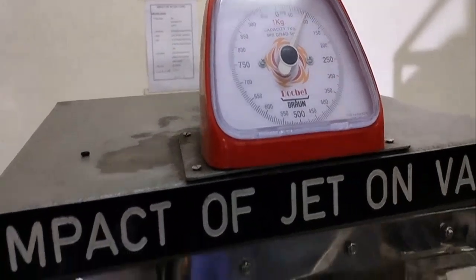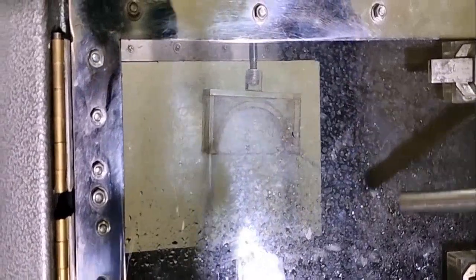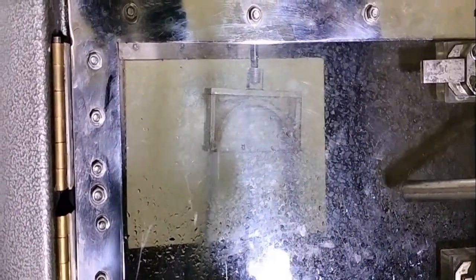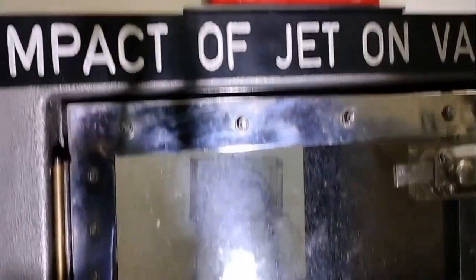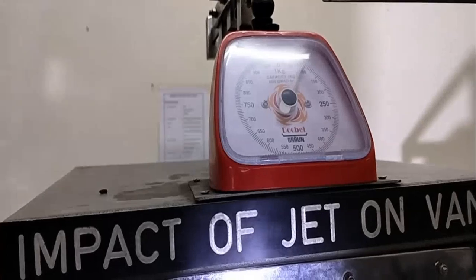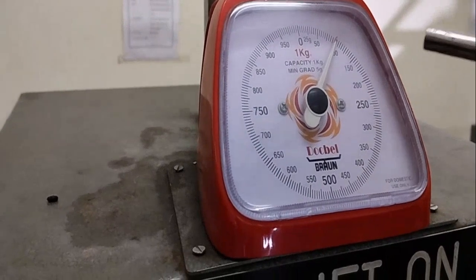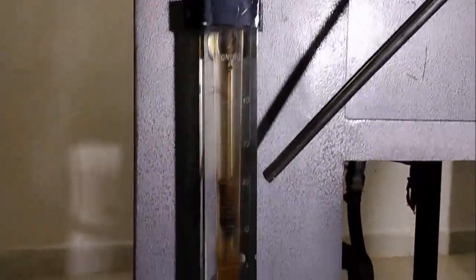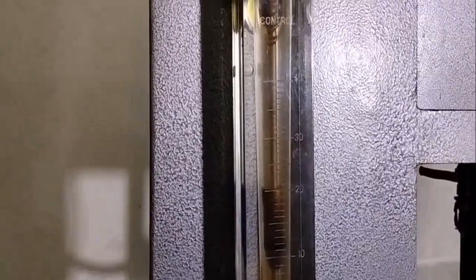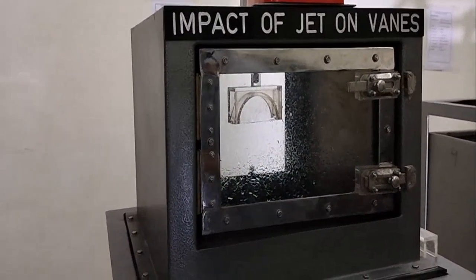Here you can see the impact of water over the vane. The kinetic energy of the jet of water impacts the vane, and that force is taken from the scale. Here it is showing 100 grams, so this should be noted for the calculation. Similarly, different readings are to be noted down: 20 LPM, 30 LPM as well as 40 LPM. The next part is how to do the calculation.